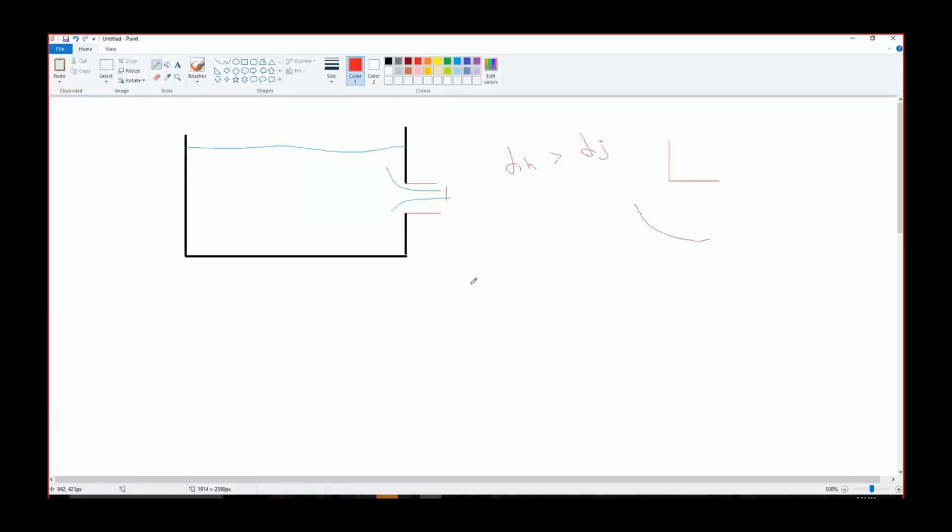smaller the area, greater is the velocity. Area and velocity are inversely related. Right? So smaller the area, greater will be the velocity. So if we are calculating our velocity based on the whole area or the whole diameter, we'll be predicting less velocity as compared to the actual velocity there. Right? So what we do, we apply a contraction factor, contraction parameter.